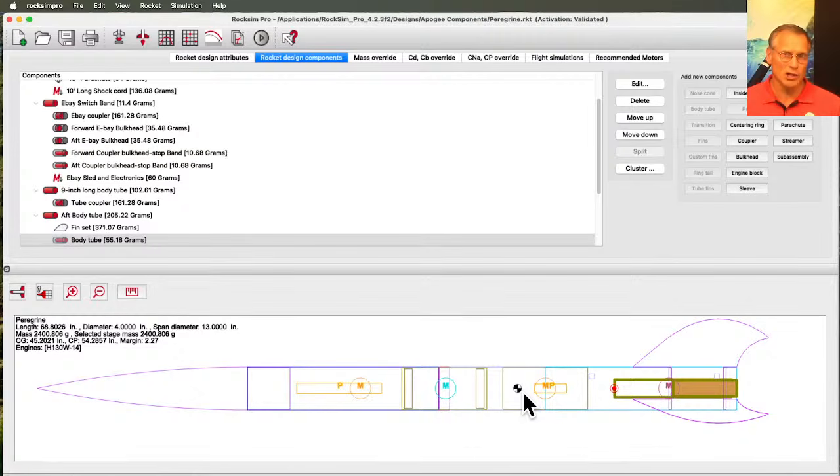And we use calibers. Calibers is kind of like a dimensionless term. It doesn't have a dimension, but what it means is the distance here in inches or centimeters divided by the diameter. So inches divided by inches, the inches cancel out. Then it tells us just a ratio of the distance to the diameter. That ratio is right here, and this is called the static margin. Ideally, we want that number greater than 1.